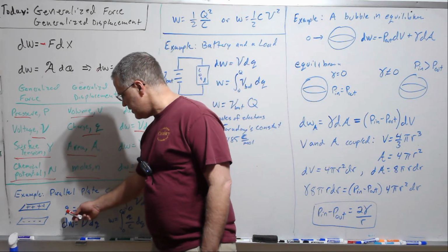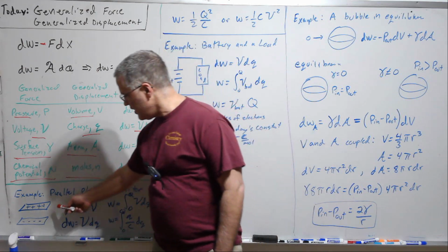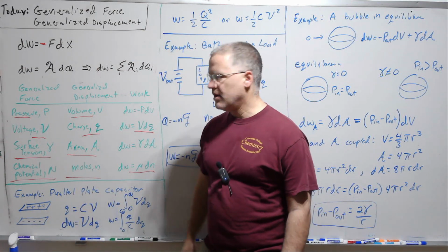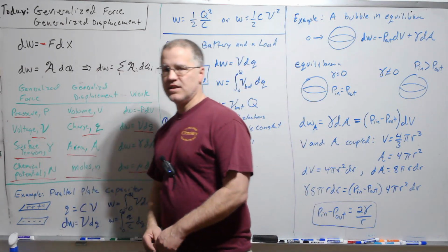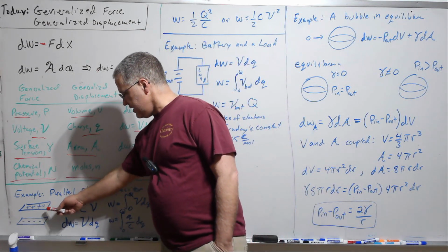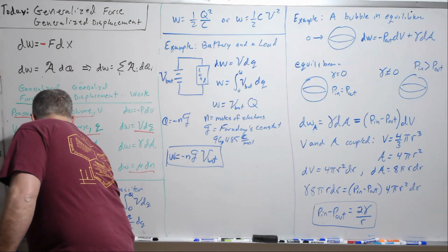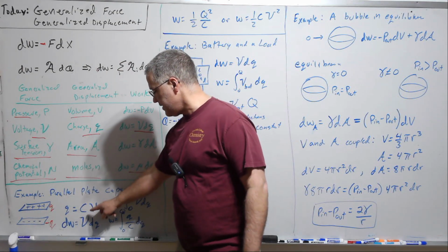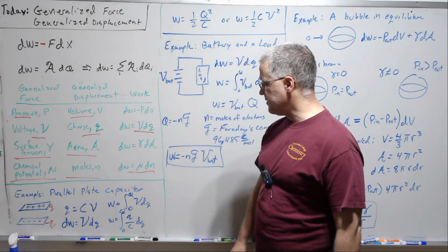But when we have a charge difference here, we have a voltage difference. So these plates can be charged up by just hooking up a battery. And you're certainly familiar with a battery. If we hook up a 9-volt battery to this, then there'll be a 9-volt difference across those plates ultimately. The amount of charge that sits on these, so there'd be a Q and a minus Q, is going to be the capacitance, the size of that capacitor, times the voltage across that capacitor.